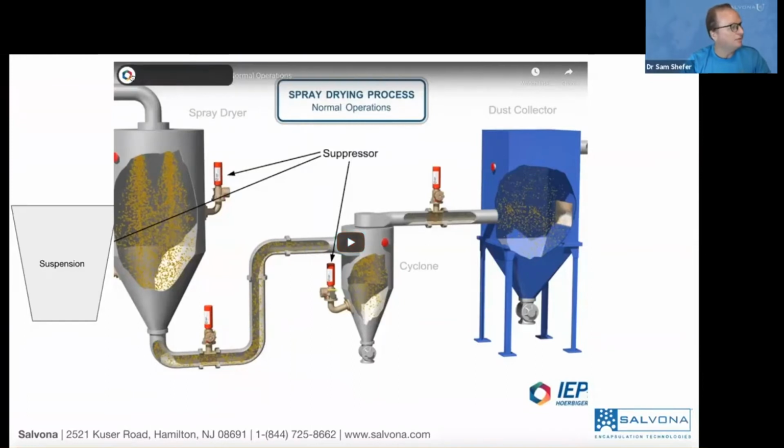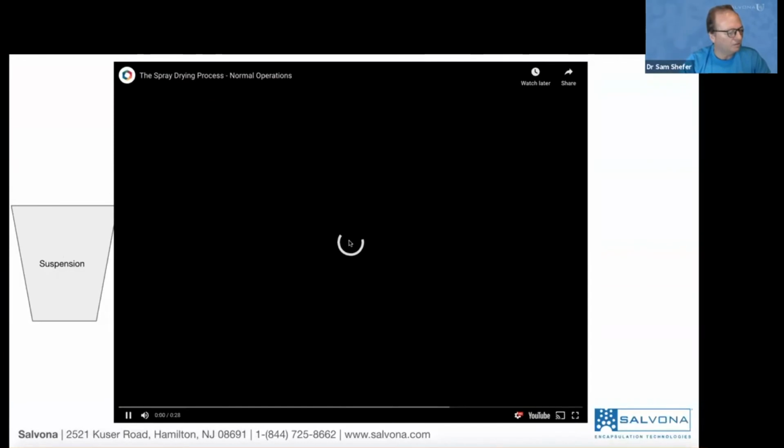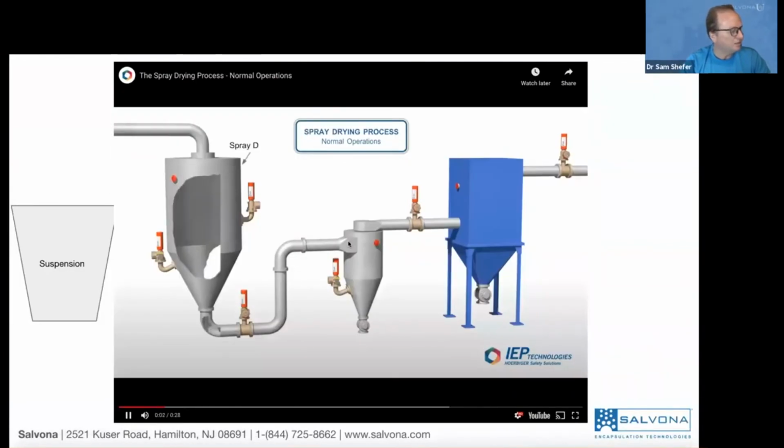What's happening here is a spray dryer head. What does it mean, in simple words? It means we spray a water-based suspension under high pressure together with hot air. The hot air and the pressure of the nozzle cause the water to evaporate. What is left is the solid that was in the suspension, now extracted and falling down at the cyclone level. So this is kind of the inside of what's happening.